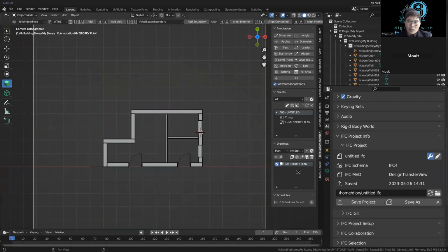Yeah, so it's quick, and I can see that now. But I looked at some of the properties. It says IFC schema is at IFC4. Could you just change it to IFC2x3, if you want to? Is it possible as well? If you've already started with an IFC4 model, I don't have a one button. There isn't a one button press to change its version. You can do it. It takes a few buttons to do it.